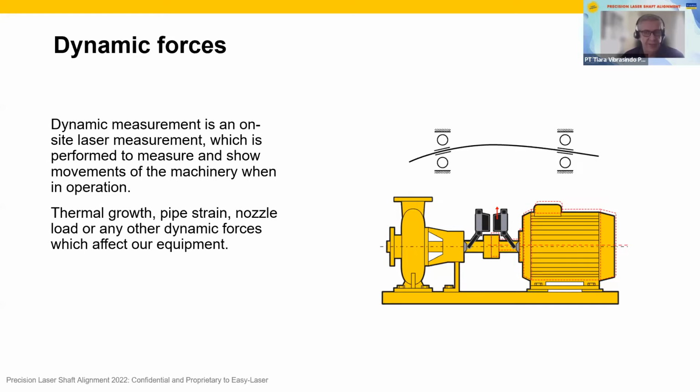So this misalignment makes a deformation of the body of the asset, and as a consequence we have also here stresses on the bearings, which leads into an increase of vibration and in a shorter operating time into a failure of the machine components, the bearings. The similar thing happens with thermal growth. The machine condition is